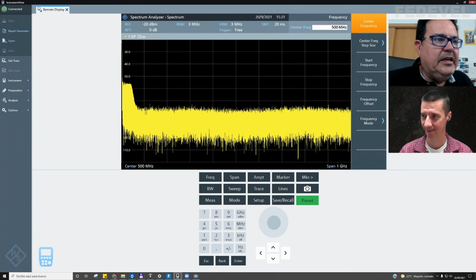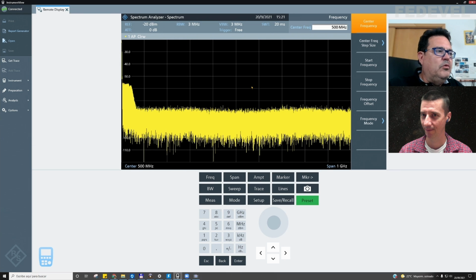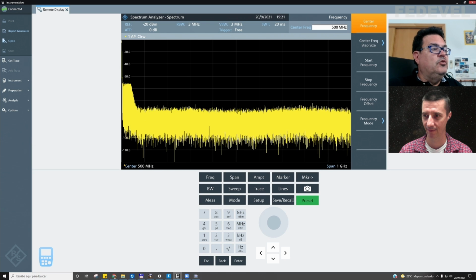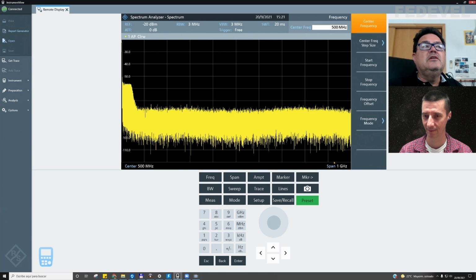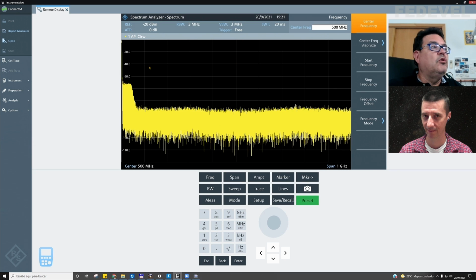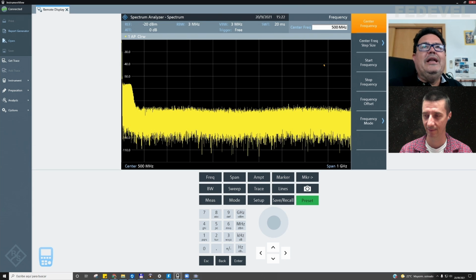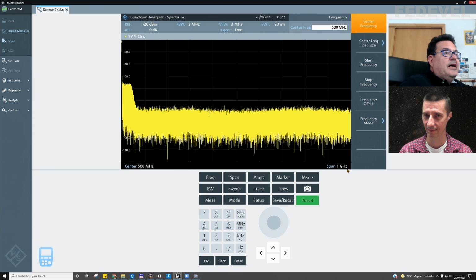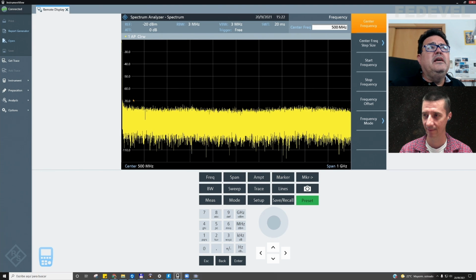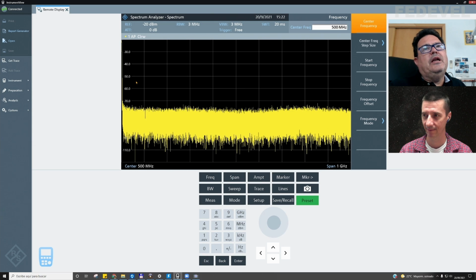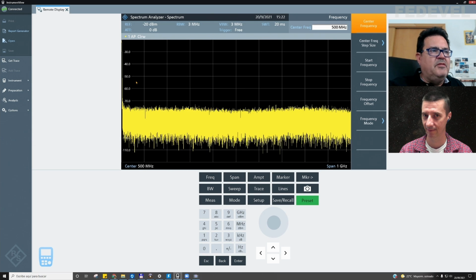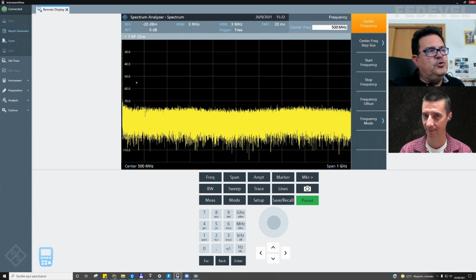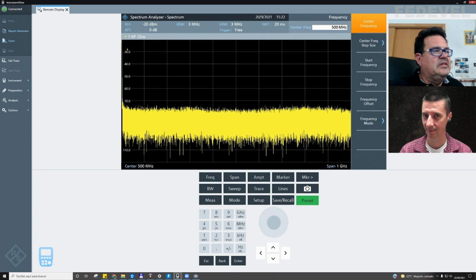This is the screen of the spectrum analyzer. You can see that now I am using the full span. In spectrum analyzers, you can specify the start and the stop frequency, or sometimes the center frequency, and what we call the span is the window you want to analyze. Now I am going up to 1 gigahertz. So for example, if I switch off my device, you can see that the low frequency noise disappears, because we are going to analyze a conducted emission problem. In this case, I will be switching the spectrum window to something like 30 megahertz.